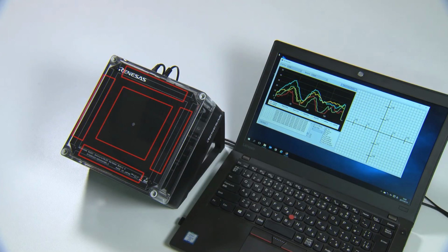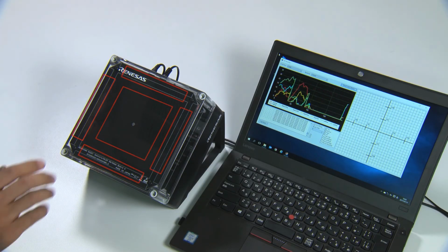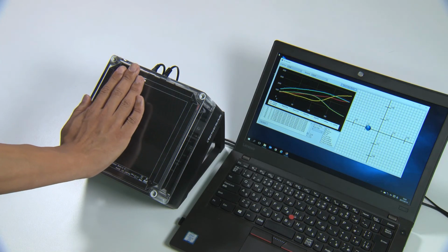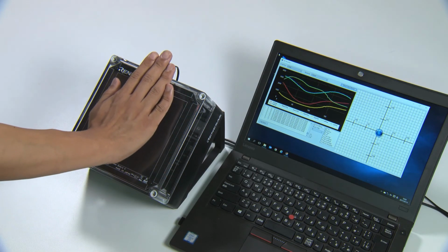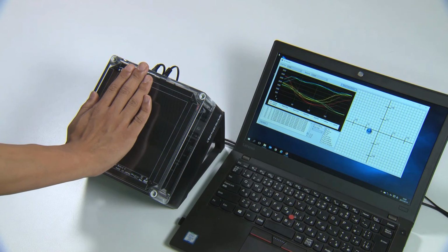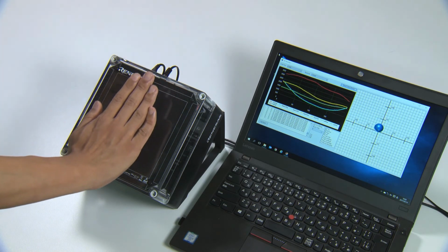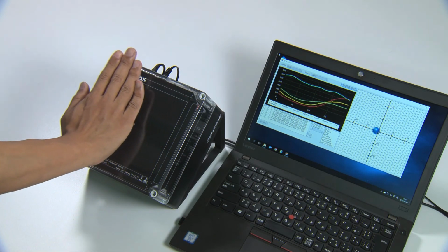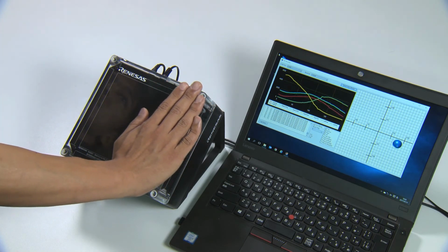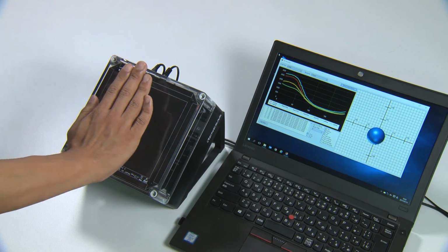The technology uses 5 proximity sensor electrodes which convert the position of the hand into X, Y, and Z coordinates within a 3-dimensional space. Any hand movement is detected as a change in these coordinates, allowing the technology to recognize a gesture motion as front, back, left, right, and up, down.